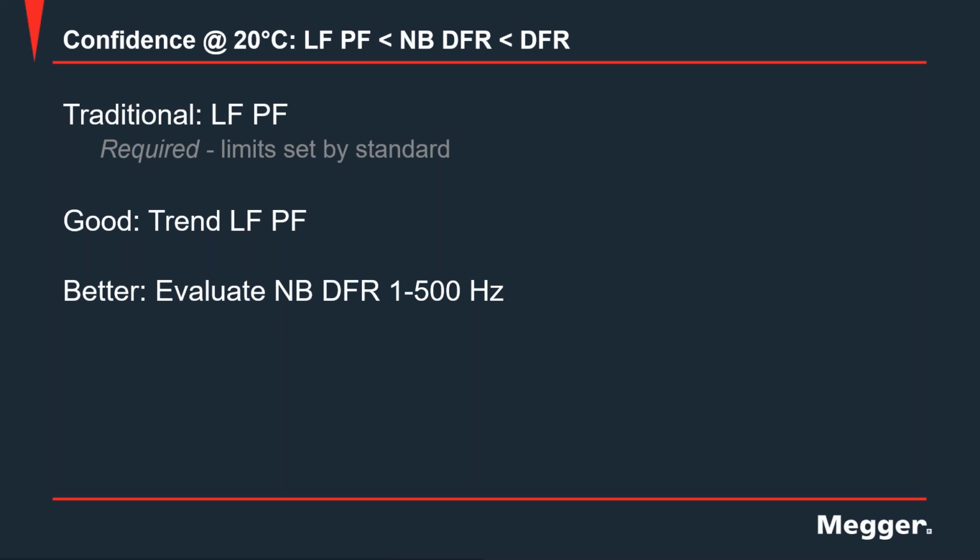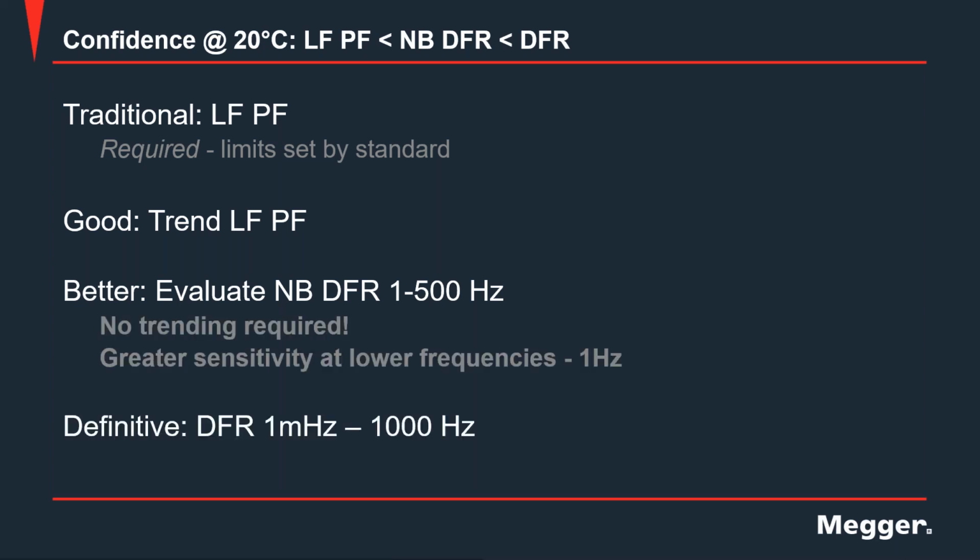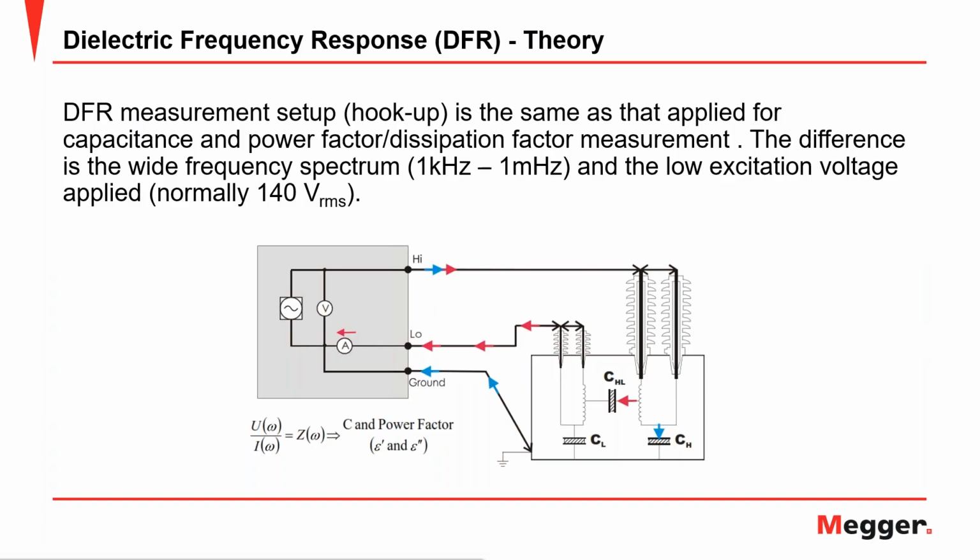So going from the traditional power factor to do some trending, to do the narrowband, and finally to do some definitive analysis of the insulation using DFR. This is the full spectrum dielectric frequency response, going from 1 millihertz all the way up to 1000 hertz. Here you can have a conclusive assessment of the solid insulation and the liquid insulation independently, and we're going to look into this separately.